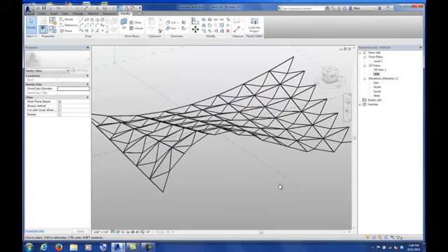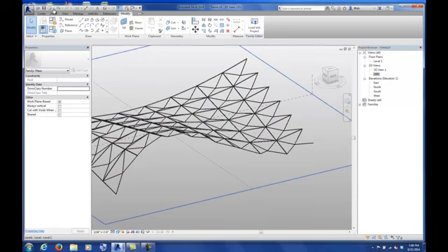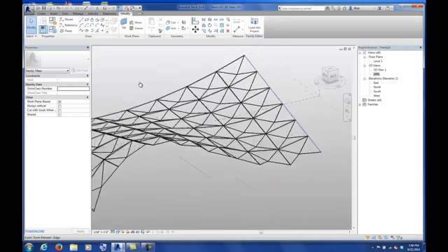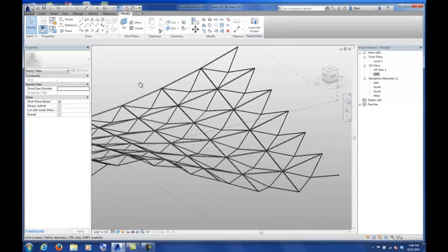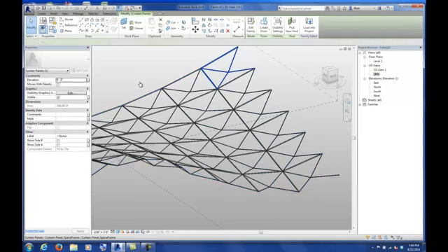Now you'll notice, and this is the last thing we'll do, I promise, that remember we made where some of the edges weren't showing, they were invisible, or we turned off the visibility of them through that parameter. So if you look at the end of my space frame, on one side there I've got a whole collection of basically the components that are missing that pipe. What I can do is tab over until I can select one of those space frame components.